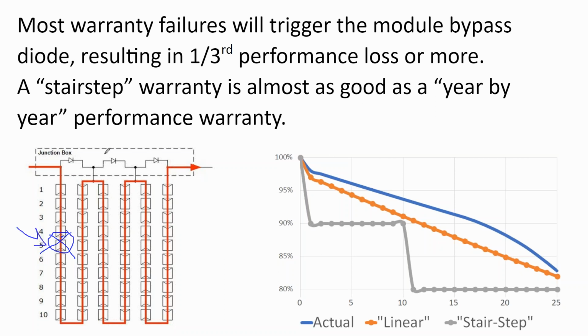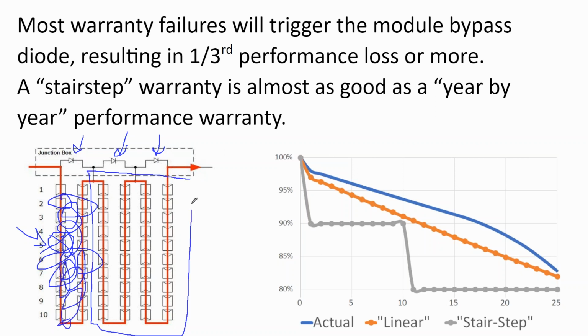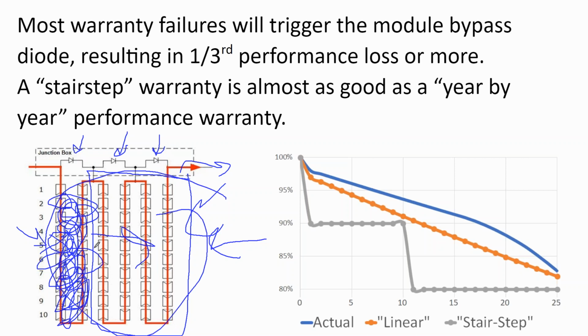What's going to happen is your solar panel modules have bypass diodes in them, and this is for shading, though it's rather puny, because often shade is more complicated than this. But it's like, okay, if this section of the solar array got shaded, then the module power output would only drop by 2/3. And it's puny because if this module drops by 2/3 on a traditional array, all the other modules in that circuit will drop by 2/3, and the voltage will start flickering, and the inverter will get confused anyway. And how often does a shadow just fall on that portion of the module and not the rest of the solar panel anyway? So it's really not terribly effective.